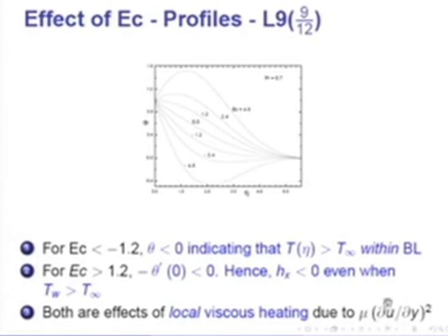This kind of viscous heating is of great concern in re-entry vehicles coming from space into the upper atmosphere, where a sudden increase in viscosity of the atmosphere would be generated. The re-entry vehicle is hurtling down at very high velocities, of the order of 5 to 6,000 meters per second, and you get enormous velocity gradients very close to the wall. As a result, the viscous dissipation term becomes very dominant, and you would generate large amounts of heat.